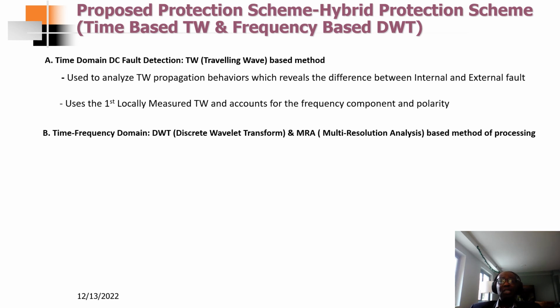That is a protection scheme that consists of a traveling wave and discrete wavelet transform in a multi-resolution analysis, or continuous wavelet transform in a multi-resolution analysis, or a combination of a traveling wave and artificial neural networks and machine learning techniques.